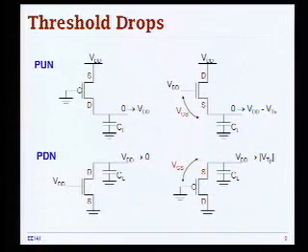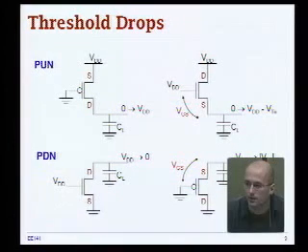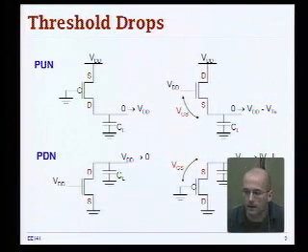Why would you want to do that? Would that be good for power? Exactly, that's a very good point. That's what I was actually just leading this into. Reduced swing gives you very good properties in terms of power consumption, because we know that power is proportional to the voltage swing on the capacitor.